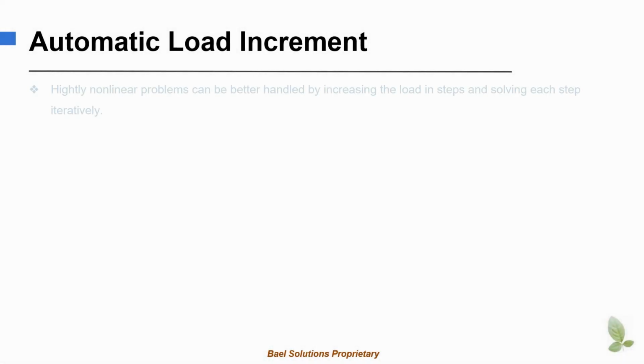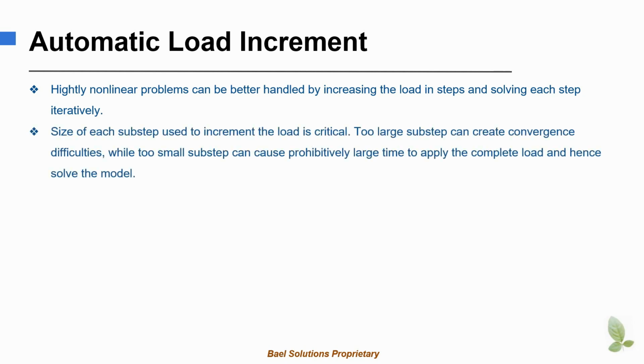In the last session, we learned that providing a large number of load increments, or substeps, can help solve nonlinear finite element models. In this slide, we are going to learn more about the substep settings in ANSYS. Selecting the appropriate substep size is critical in a solution.